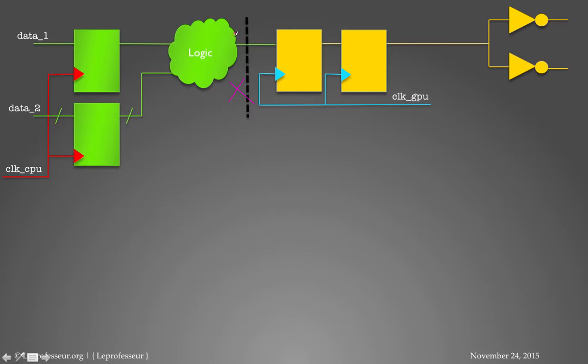Let's say this is the D signal here. It is the typical nature of a combinatorial signal that it might have glitches, or go up and down too quickly. These glitches will cause the flops in the receiving clock domain to go into the metastable state too often, so that increases the probability of failure.